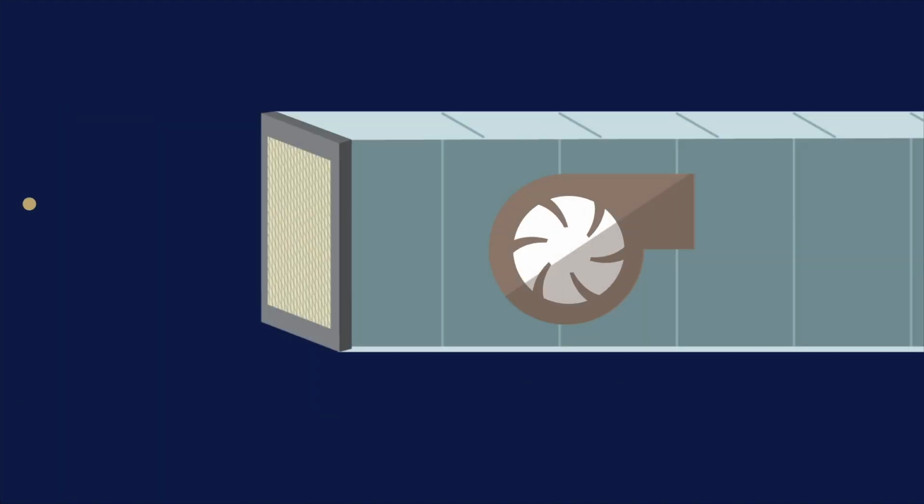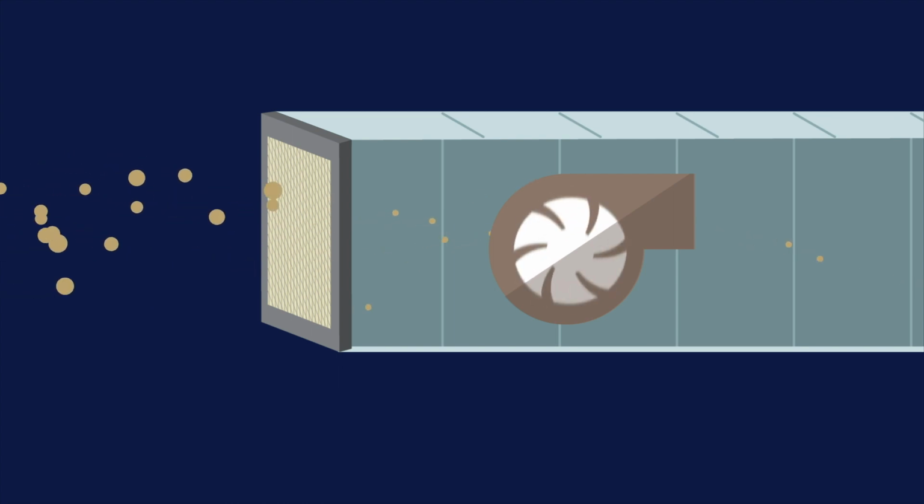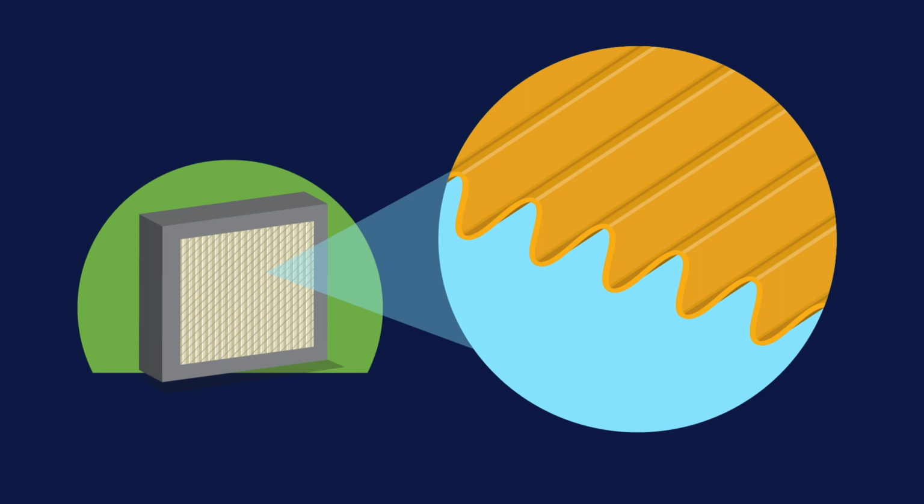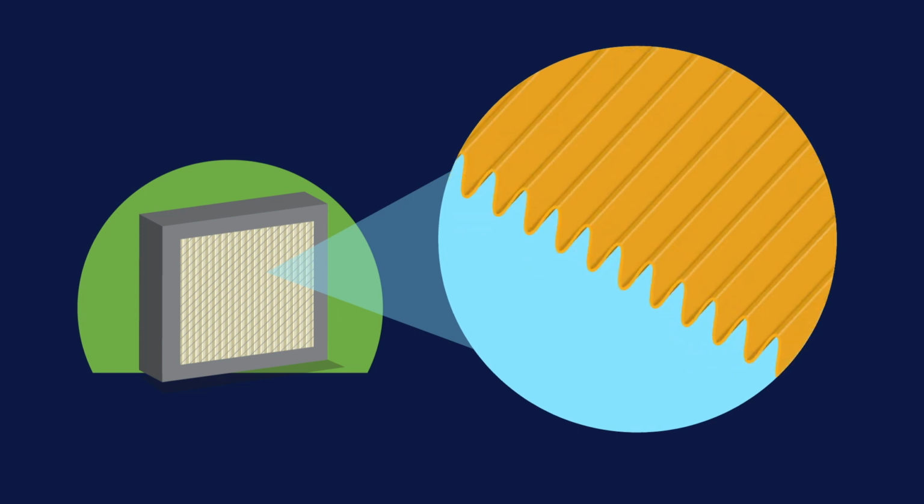You may be concerned that a fan motor not originally designed to work with a MERV 13 filter could struggle with the additional resistance. Filter manufacturers address this concern by making lower pressure drop, high-capacity versions of MERV 13 filters that have more pleats in the filter media.